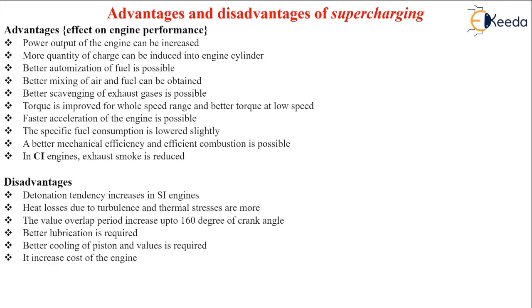Then also the SFC, that is the specific fuel consumption, in a supercharged engine is a little bit lower. Also, mechanical efficiency and combustion efficiency are expected to improve. And in case of a CI engine, exhaust smoke is reduced. This methodology cannot have only advantages.